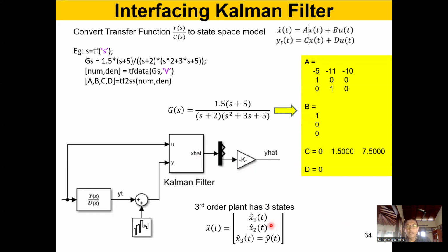And then you can see it over here. This is a third order system, so it produces three states, right? And out of that, you get the third one over here. Here you can see x1 hat, x2 hat, and x3 hat. I use hat whenever the signal is an estimate, okay? Somebody is estimating the signal. So that is what this hat means, right? X3 hat in this particular configuration is Y hat T. In this format, when you have the non-zero elements at the top, you have X3 as YT. So remember that order: X1, X2, X3.